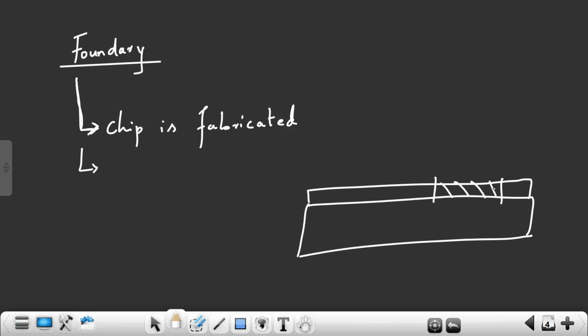Oxide removal doesn't happen by using some grinding machine. It happens by treating this oxide layer with what? Acid. Treat this with acid. So this region I will cover through a photoresist mask, and this region is not covered by photoresist. This region is exposed to acid, and this is removed away. So removing some portion of the material in the fabrication unit is done through acid.